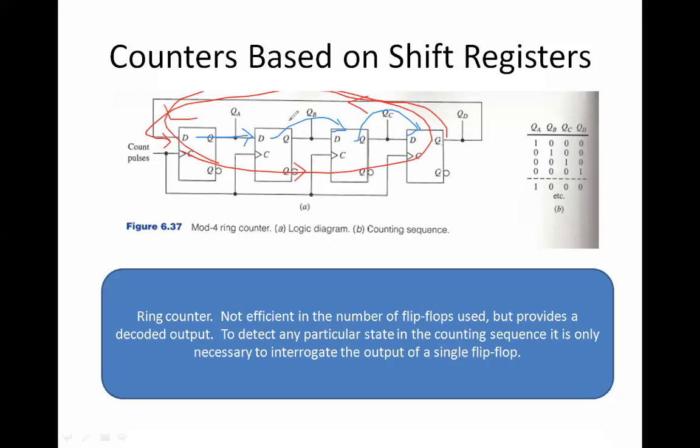Right? So it's acting like a ring. Clocks are connected together, okay, and hence they are called synchronous. So all the clocks are connected together. Many modern chips do not have the Q bar, because it's a waste having a Q bar. Anyway, the Q bar is the opposite of Q. So if you really need Q bar, you can connect Q to an inverter and take out Q bar. If not, they do not want to waste resources in building a separate pin for Q bar.